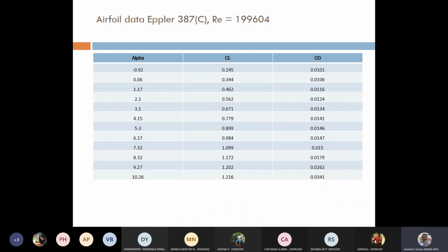So you can take those series and then pick up, as per your requirement, what the wing span should be, what the chord should be. Okay, so you can go ahead with the particular files. And if you have selected the particular files, then at least you can analyze all the CD, CL, or maybe the CL versus CD, all those things, correct? Then CL versus angle of attack. So this is the idea, all the parameters should get analyzed first.